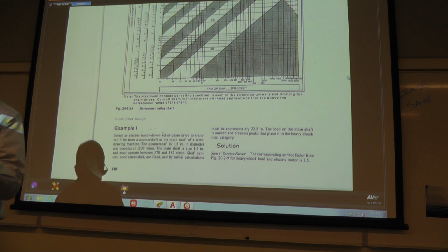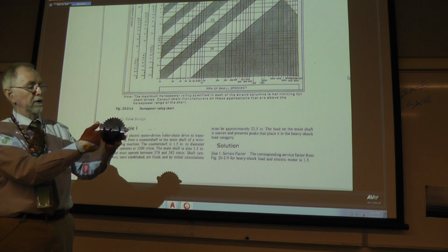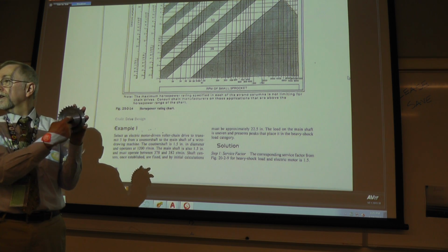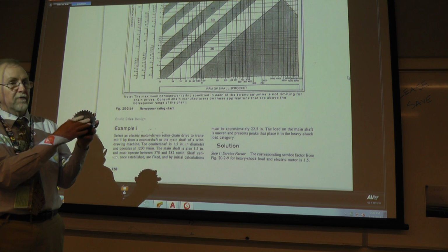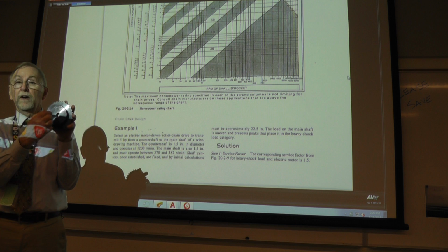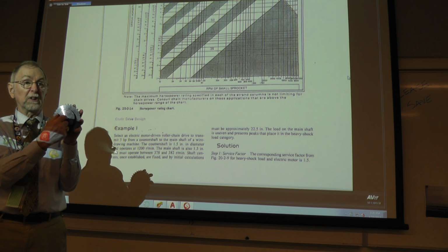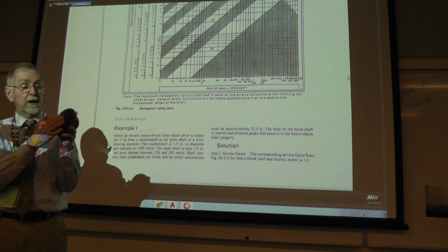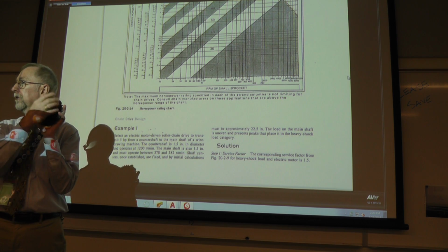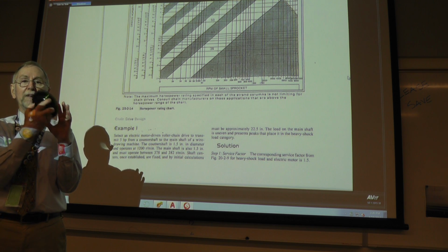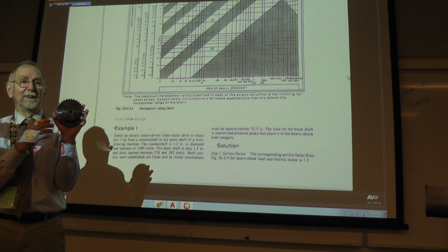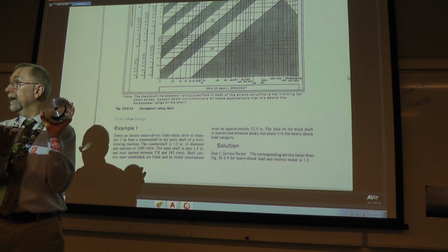And then this would be a sprocket. This sprocket has a hub, an outer diameter here, and then it has a bore size in here. Now, this has got enough material on it that if this bore was too small for the motor, I could machine it out, I could drill it out, ream it out, and use that. There's no keyway, there's no hole drilled in here to put a big old long set screw. There's no mechanical way of connecting this to a shaft. It would just literally spin, which is sort of a blank.